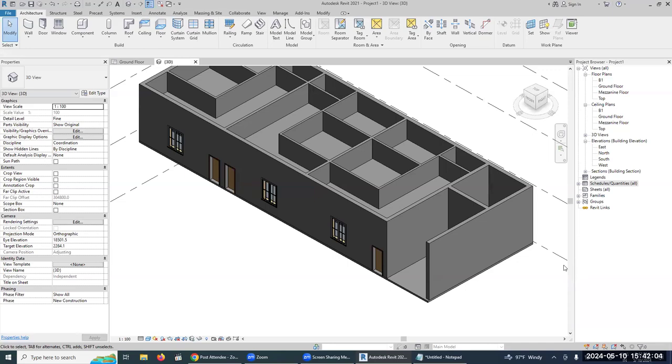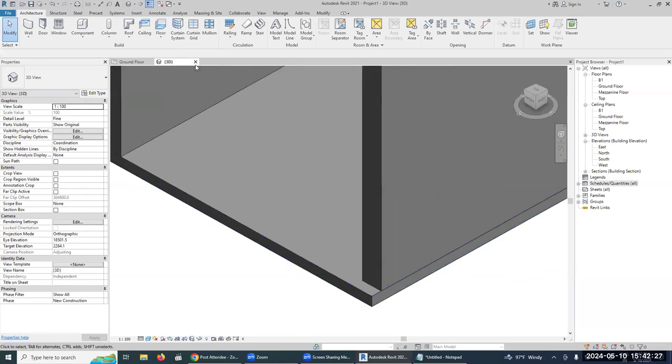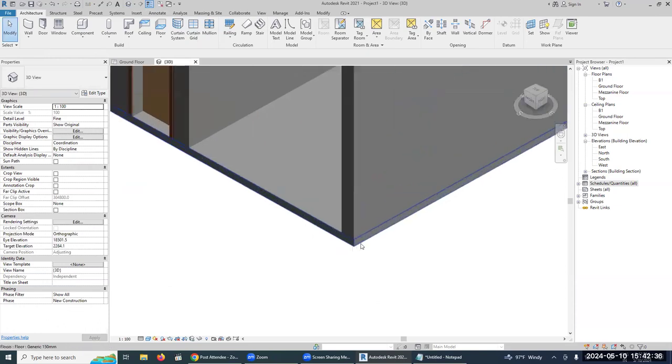Okay. That time when you created a new one. Okay. So why is this wall not flushing? Look at the wall, it's not flushing. It's a resistance. You have to extend that one, no? You have to extend. My one also is like that. You have to extend this wall. See, here is a gap that is to be extended, no? You can take your AL align from here to here. You can extend the wall, and then the wall will be exactly on the floor.